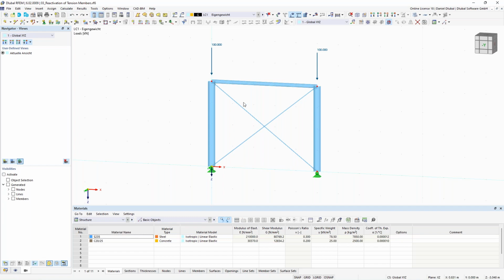But what we also have to consider is that when I take a closer look at the deformation of the structure, the columns will get compression forces and will also get shorter. But also in the first iteration calculation, both bracings, so both tension rods, get compression and they would fail.